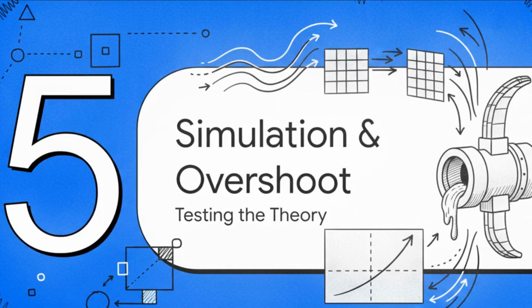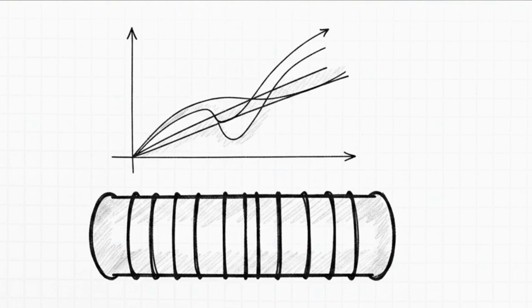Let's hit step 5, MATLAB simulation and overshoot. A MATLAB simulation is absolutely essential here. Why? Because human brains simply cannot calculate 30 mathematical nodes interacting across 600 seconds of continuous transient phases. The software discretizes the 0.6-meter barrel into 30 spatial nodes and runs an explicit finite difference method. Over an initial 10-minute, so 600-second, transient phase, MATLAB visualizes exactly how the thermal zones drag each other upward. It mathematically proves our analytical model is spot on.